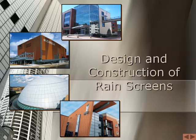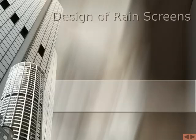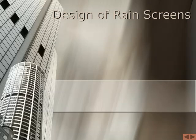Design and construction of rain screens. Design of rain screens. Rainscreen facades do not need special materials except to withstand wetting and drying cycles without deterioration. Even wood may be used as a material for rainscreen facades as long as it is protected with a waterproofing material.